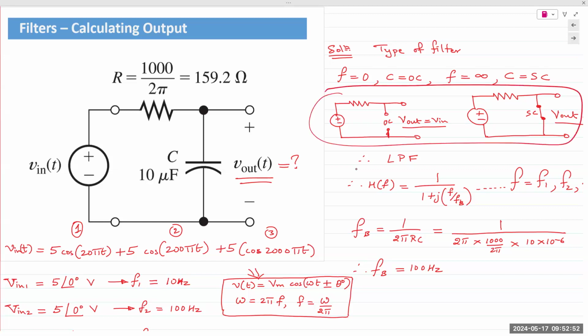Well, the quick answer is, how do I know this is a low pass filter? Because I just did it. But in any given circuit, we can plug in the component behavior at F equal to 0 or F equal to infinity, and we perform this analysis where I can determine whether I receive output or not.